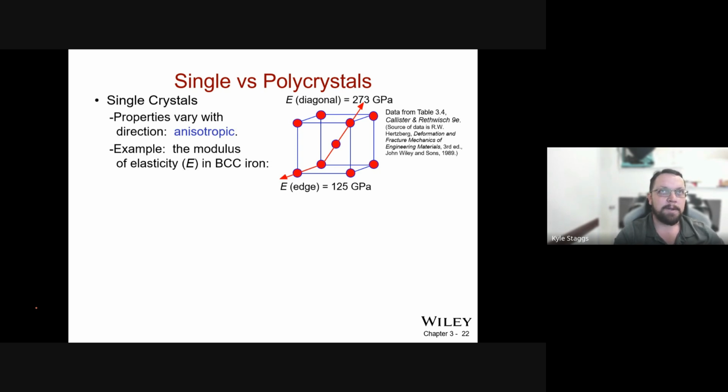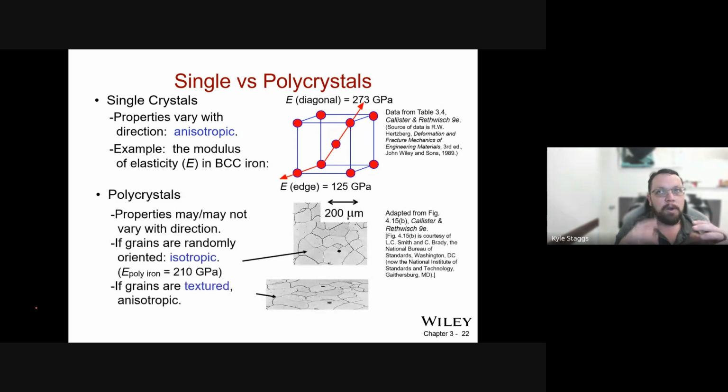So same material, pulled in a different direction or put under a different kind of stress, is now half the strength of what it would be in the correct orientation. So the grain structure and orientation relative to whatever your design application is matters tremendously.